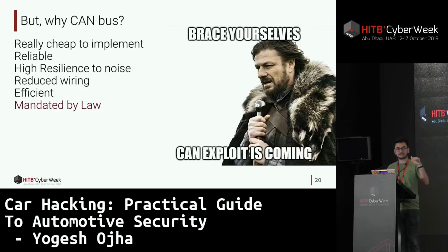So when the voltage is sent, it drops the same amount of voltage on one line and increases on the other line, either in the CAN high or the CAN low. This is what makes it tolerant to noise. One of the reasons CAN is efficient is that CAN packets are normally prioritized through identifiers in such a way that those with the highest priority are not interrupted.